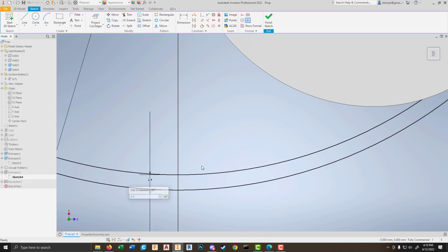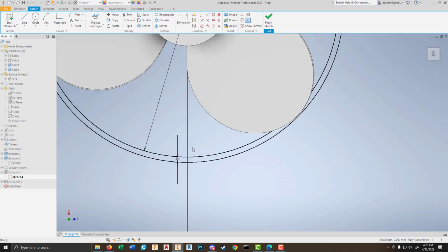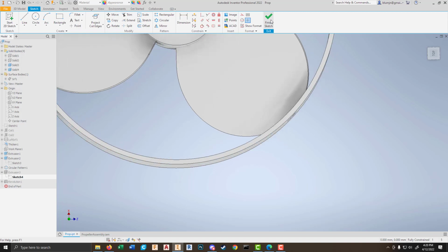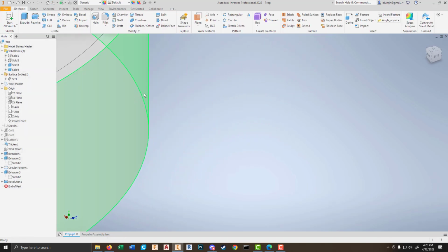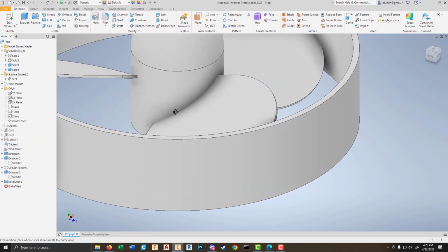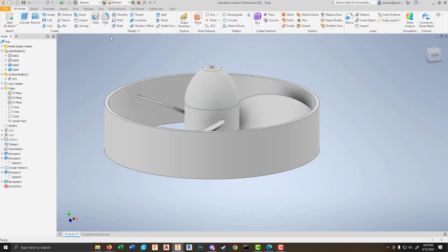And we are going to make this guy 2.4 millimeters. Now, why 2.4? I know that we have a 0.4 millimeter nozzle on our 3D printer. So I want this to be in multiples of that number, just so that it divides neatly. And now when we hit Finish Sketch, you will see it's going to update, and that little bit of geometry disappears. That is all good.